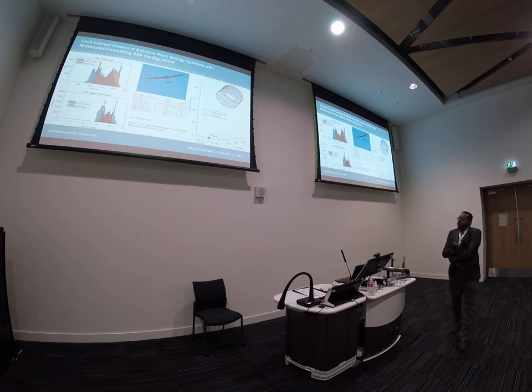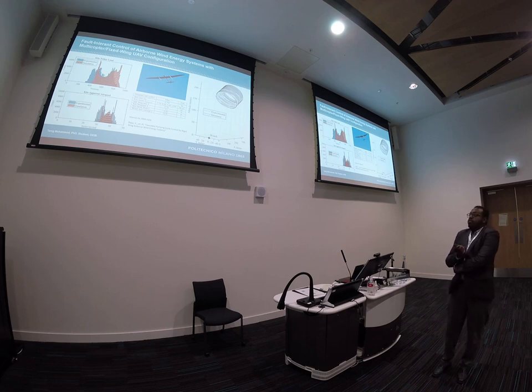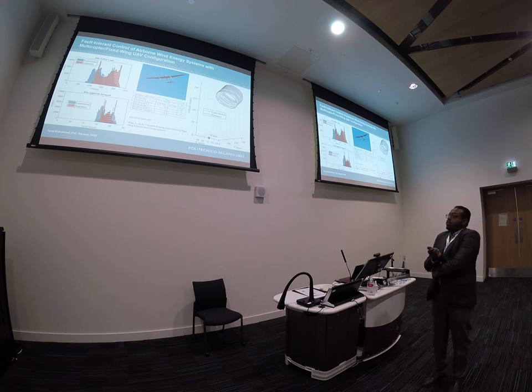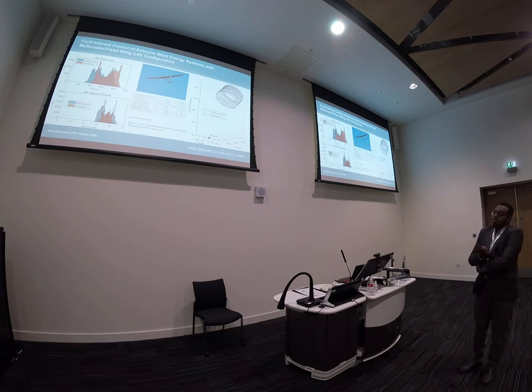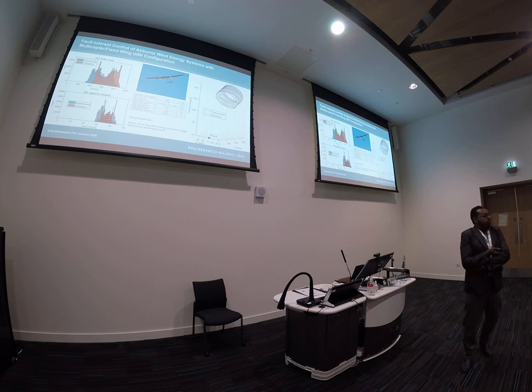As you see here in the histogram, the first figure shows the load on the tether, and what we get from the simulator. In the simulator, we get from 400 Newton up to 900 Newton with two peaks at around 500 and 900. And in the experimental data, we get quite a similar histogram. So we consider that this is a good match.